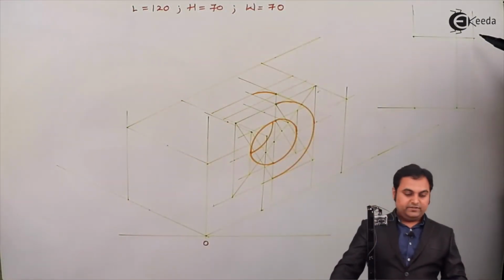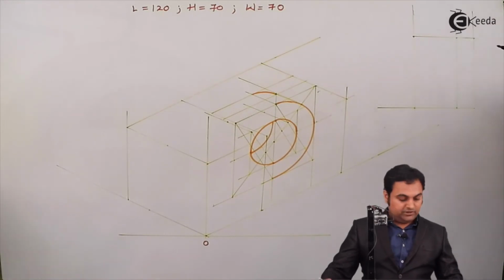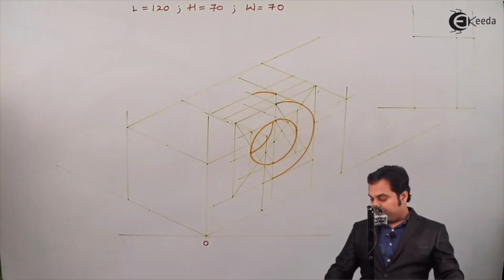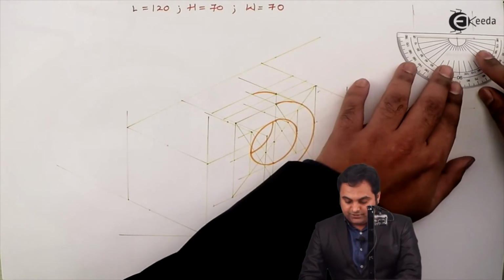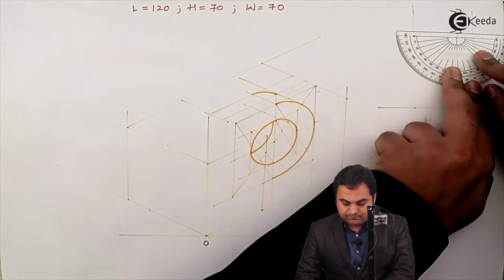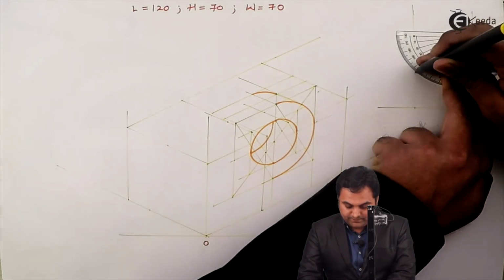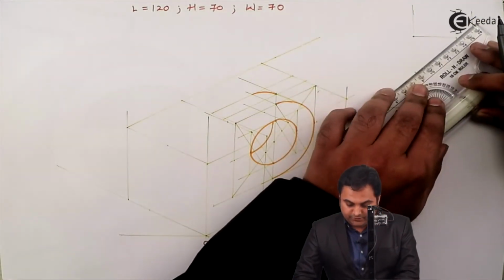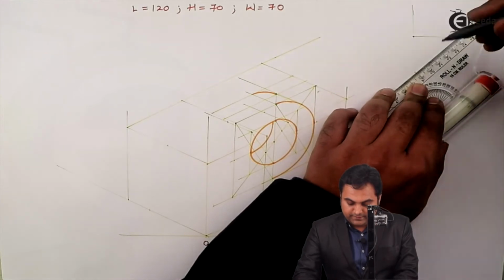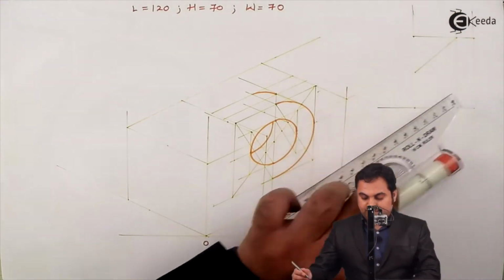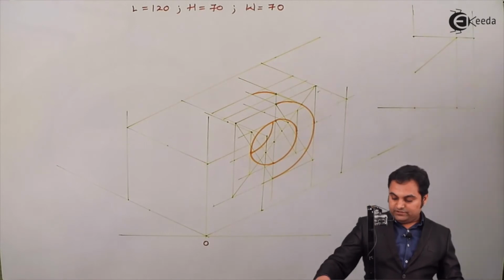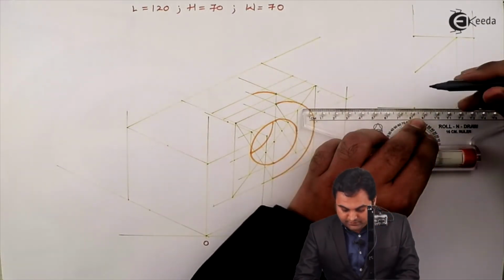Next, after getting this 15 mm at the top, now from here I'll measure the angle of 45 degree. That is from this location, I'm taking the angle as 45 degree, and then drawing this line which is inclined. Now I get the height of this slope and making this surface dark.